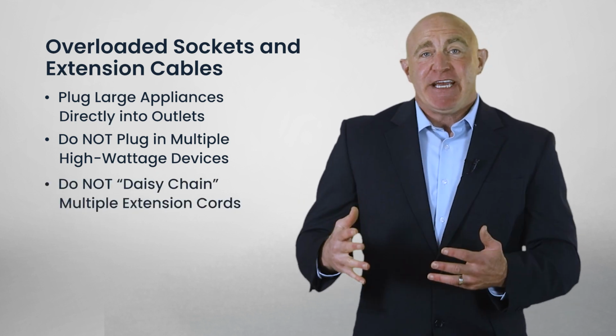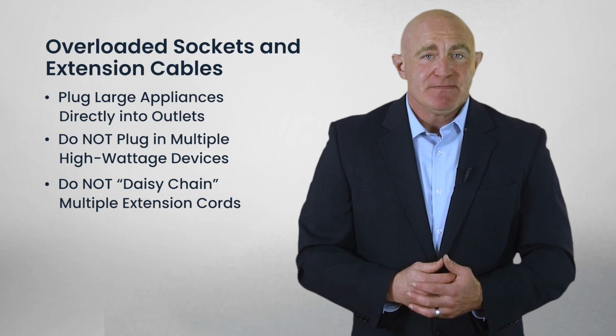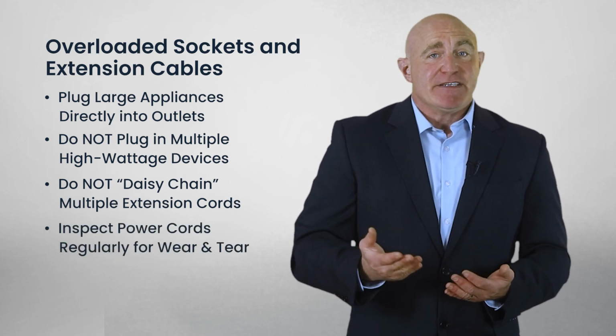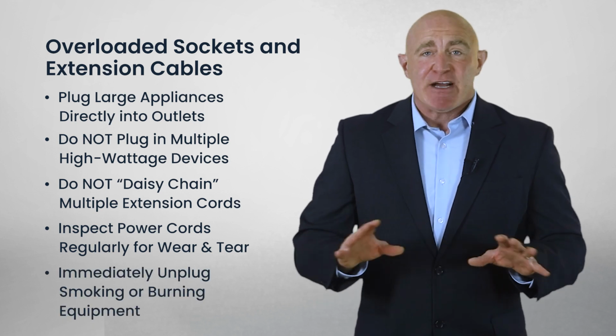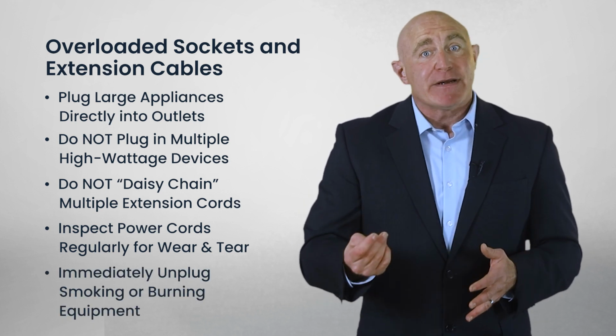Do not daisy chain or connect multiple extension cords. Inspect power cords regularly for wear and tear. And immediately unplug or de-energize any equipment that causes smoke or a burning smell.